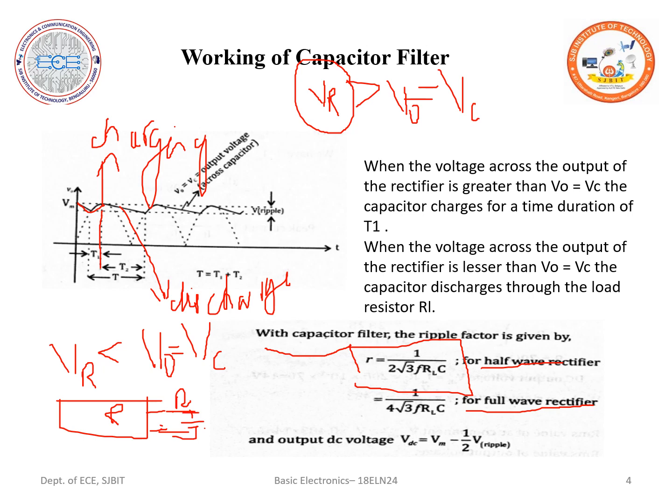Once you incorporate the filter circuit, it is going to remove some amount of the ripples present in the DC component and make my pulsating DC a pure DC. So it is very much needed to calculate the ripple factor once you connect the filter circuit to the rectifiers, and to know the ripple factor with and without the filter.